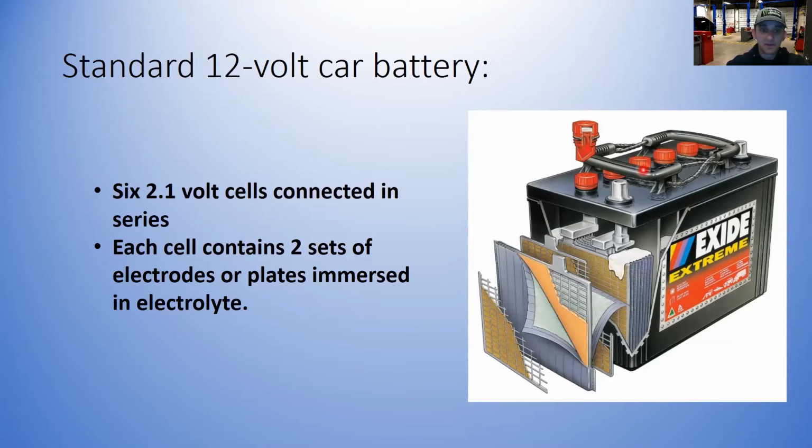Most people have the common mistake or misconception that 12 volts, when they see 12 volts on an open circuit test on a battery, that it is fully charged. It's not. It's actually a discharged battery. 12.6 volts is a fully charged battery. 12.4 is about 75%, and so on down the list.